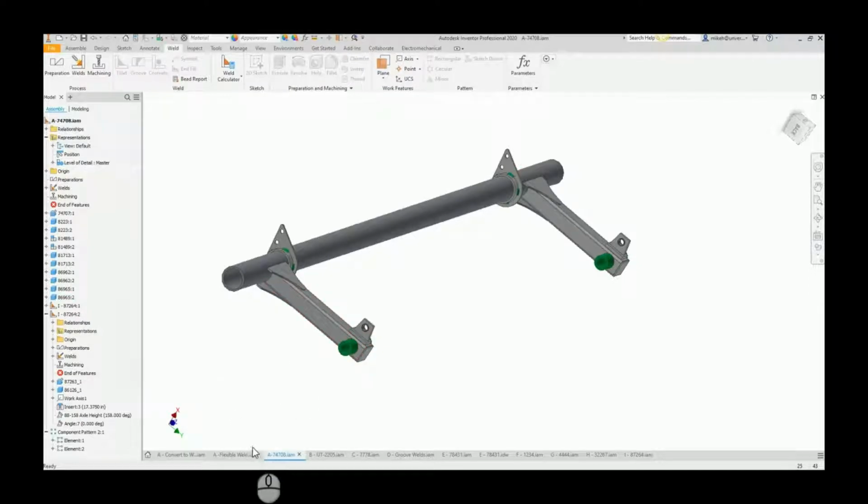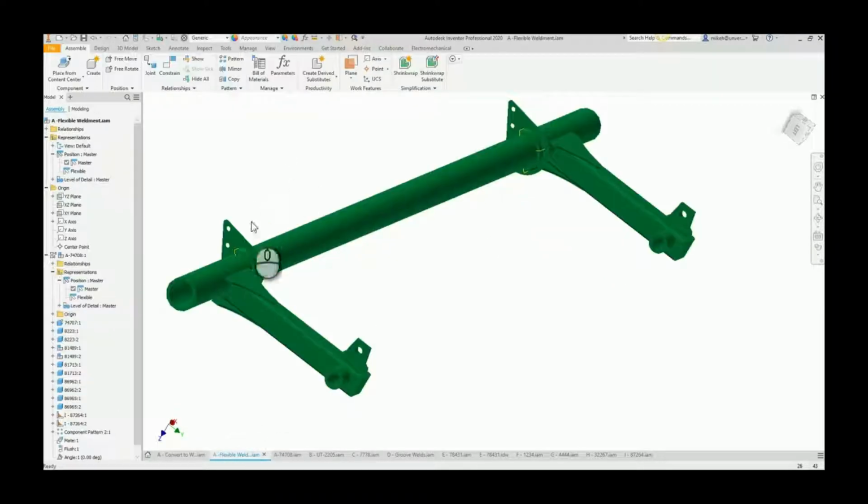And then one last item is, as you noticed, you can have weldments flexible. In this case, this kind of acts as a hinge, or basically like a bearing or bushing. So we can leave this unconstrained, and it can be flexible, because in reality, at the next level up, we want this machine to be able to be flexible.